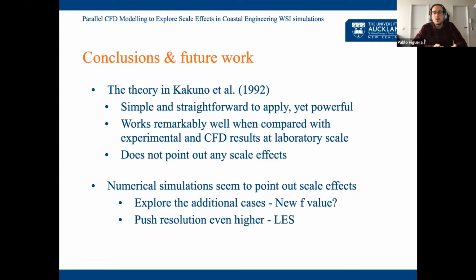And how are we going to do that? Well, we're going to explore additional cases, probably trying to fit a new F value to see if the F value is affected by scale effects. And we want to at least run one additional simulation pushing the resolution higher so that we can see all the different effects, even going into LES simulations.